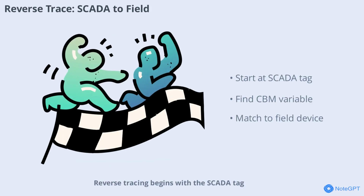Reverse tracing begins with the SCADA tag, finds the corresponding variable in CBM, cross-references where it is written, locates the hardware I/O channel, and matches it to the wiring diagram to identify the physical device. This approach is essential for troubleshooting and verifying that operator commands are correctly executed in the field. It provides a clear path from the control room to the plant floor.